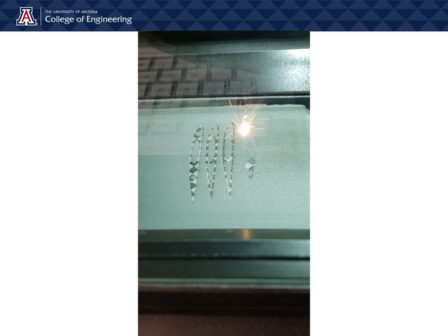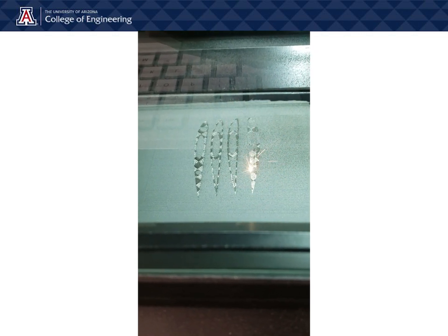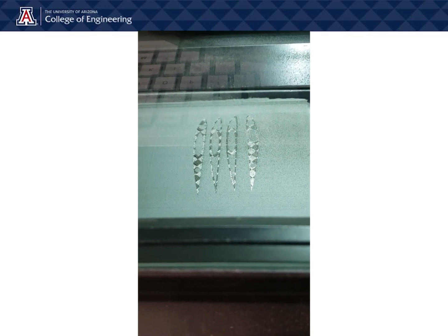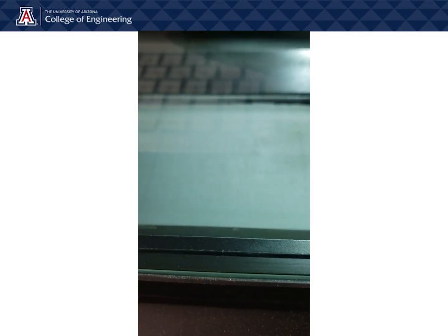SLM is an additive manufacturing technique where a high-density focused laser beam will selectively scan a powder bed to melt and solidify layers that are stacked to create a functional model. Due to the high precision and wide array of usable materials, SLM printing is ideal for aerospace applications. The printing process can be seen in these videos provided by Cameron.